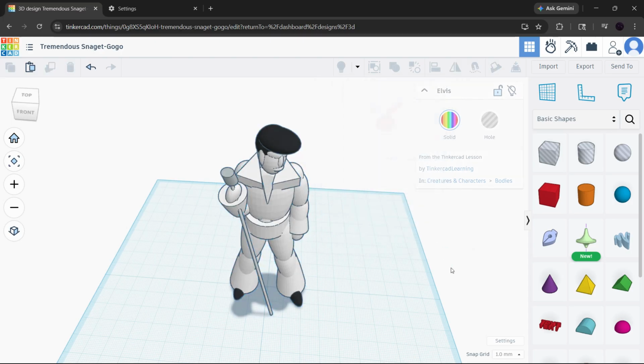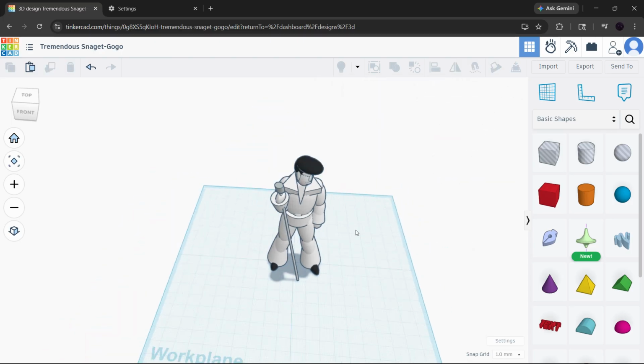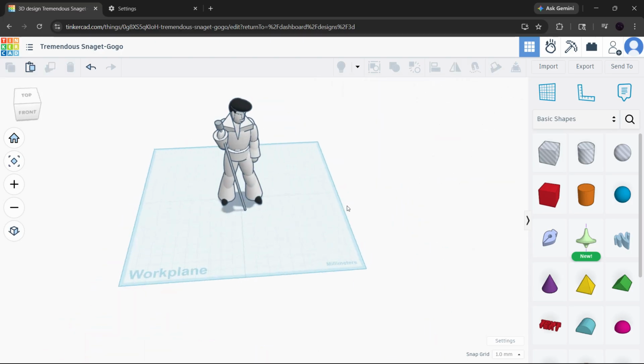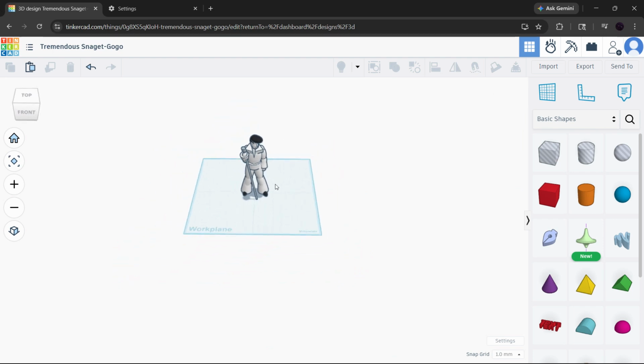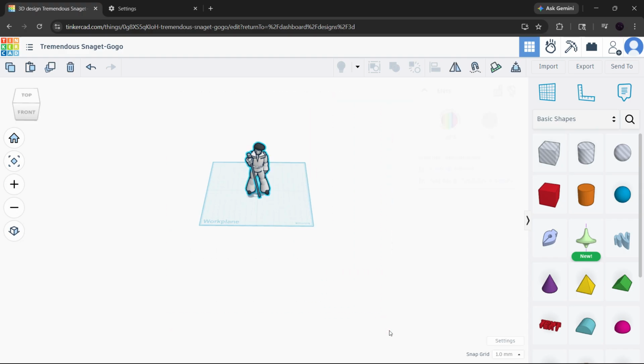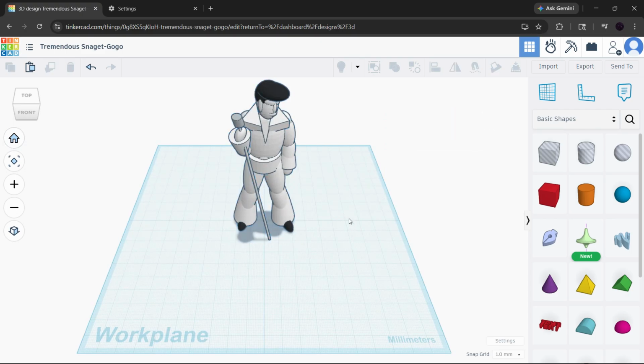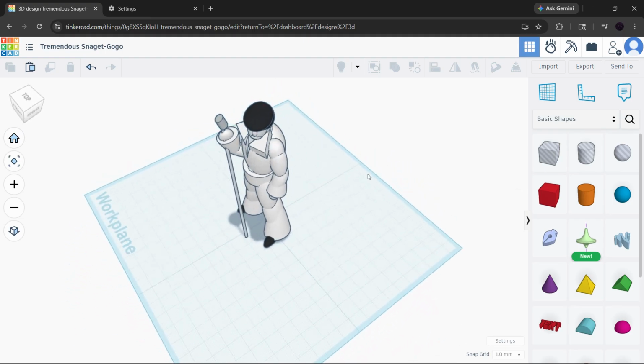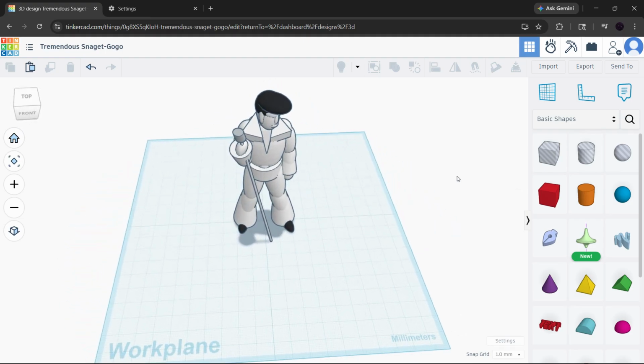While you're here, zoom out and look around the workspace carefully. Sometimes there are tiny stray shapes, phantom objects, or accidental pieces hidden far away from the main model. Even if you can't easily see them at first, those microscopic extras can confuse the export engine and make it hang while it tries to calculate the final mesh. If you find anything out of place, delete it. Also keep in mind that complex holes, intersecting parts, or shapes overlapping in unusual ways can slow the export process down a lot.